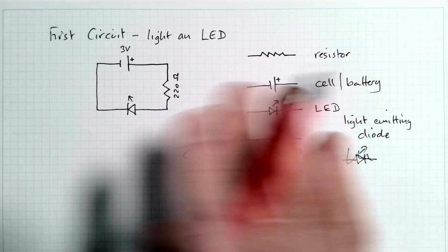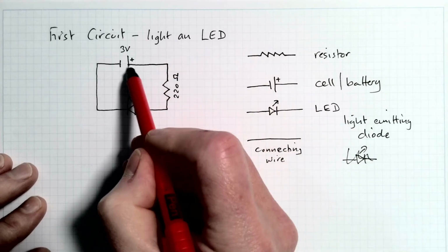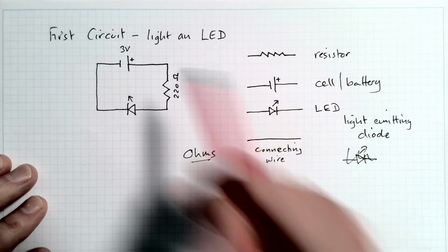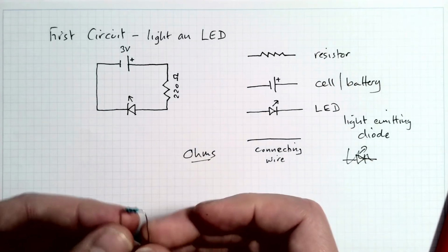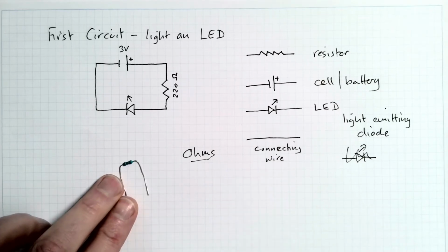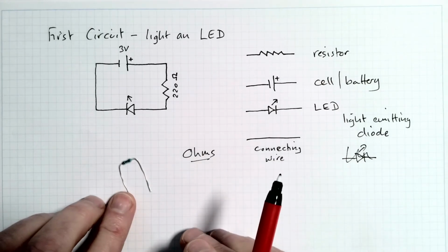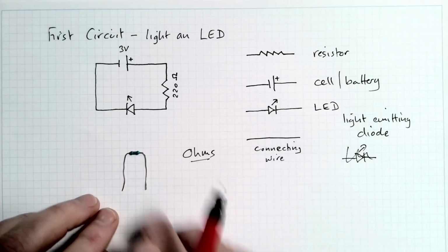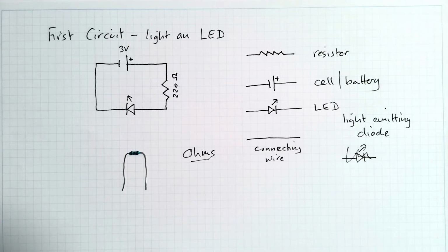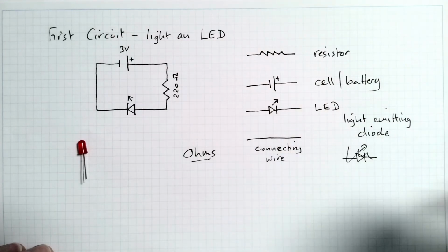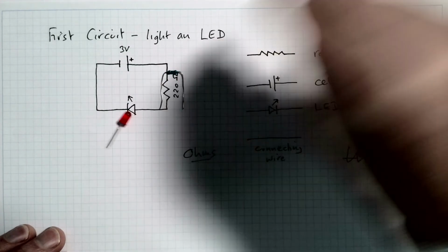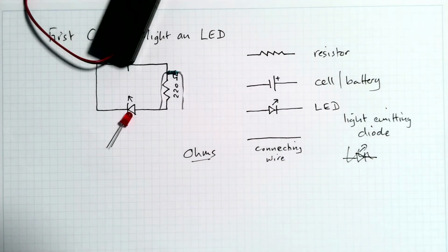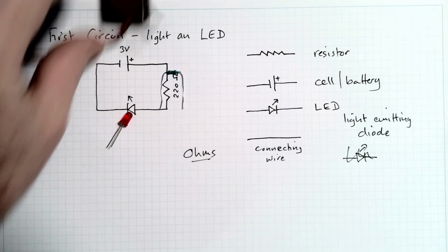Okay, so that's the circuit that we're going to build, so let's have a look at it. We're going to take our positive current out and we're going to pass it into a resistor. So let's get a resistor out and we'll have a look. They're a little bit hard to check for the values because resistors have little bands on them that tell you what the value is in ohms, their resistance. And we'll connect this into the breadboard like that. The most important thing that we have to remember though for LEDs is, when we get the LED, this is the LED, there's the resistor, we'll put the resistor there, and we have our power supply, which is going to be the battery pack with its 2 pins that we connected up in lesson 1.